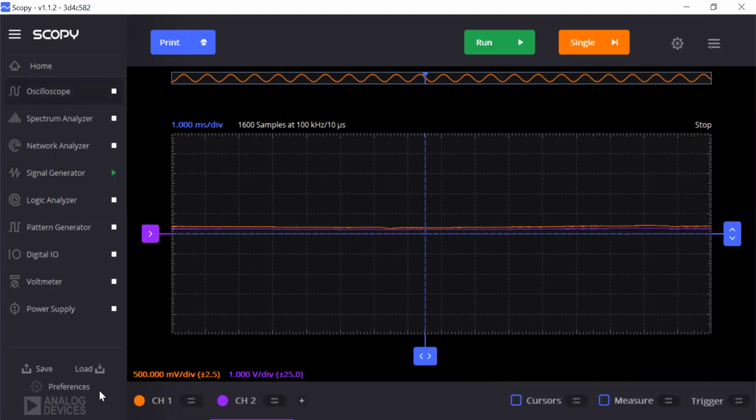And right now, nothing's being measured. So down in the lower left here, you saw this in the voltmeter, we have a channel 1 and a channel 2. We're going to use both channel 1 and channel 2. So it indicates in the lab that we want to measure our input signal, which is the W1 signal, and then our output signal. In this case, our output could be the voltage across the capacitor or the voltage across the resistor, or whatever the case may be. So you want to make sure both of these are checked on.